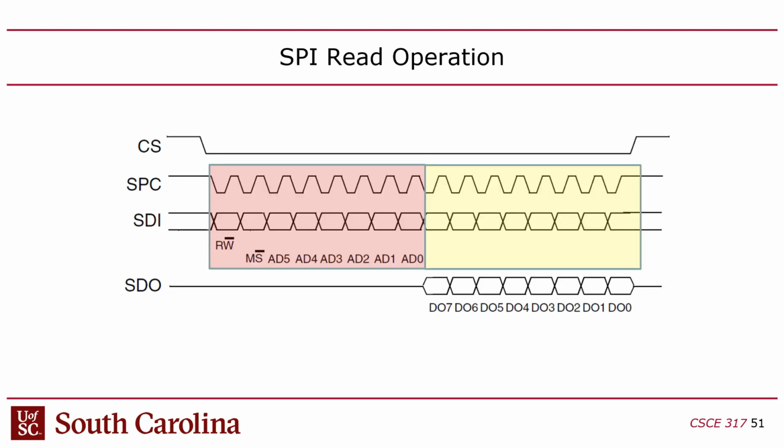Okay, so here's an example. This actually came right out of a data sheet for an accelerometer or something. You can see that the slave select, or chip select, in this case, sometimes the terminology is different, is low now. Remember, it's active low. So there's 16 cycles that this is low, which performs 2 exchanges. The first exchange is the address, and the second is the data.